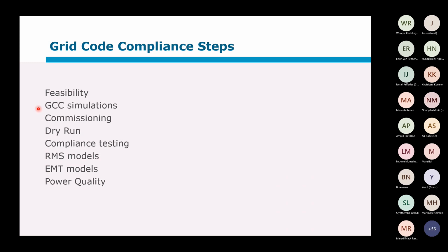Now, then there's a few steps in between these. Of course, the design is done, and then they start with the construction. The commissioning, we've now just discussed. What does the commissioning typically entail? Usually during commissioning, they would go through so-called dry run tests, which in essence test all the requirements of the grid code before RETEC is called to come and witness these tests.